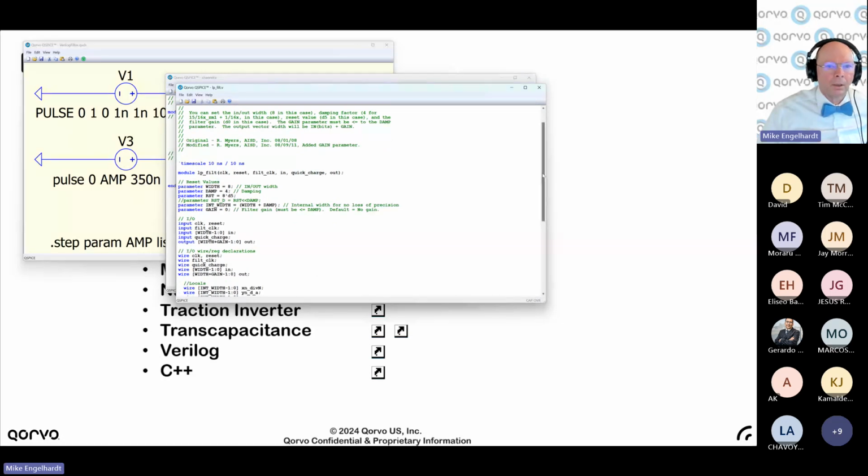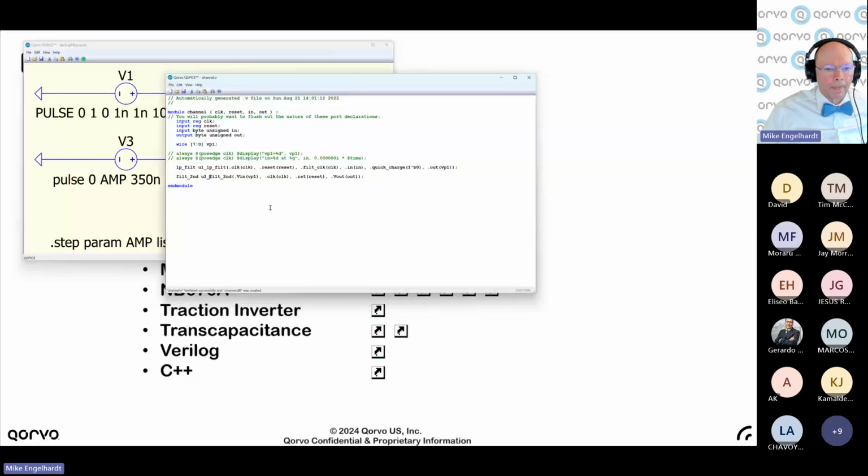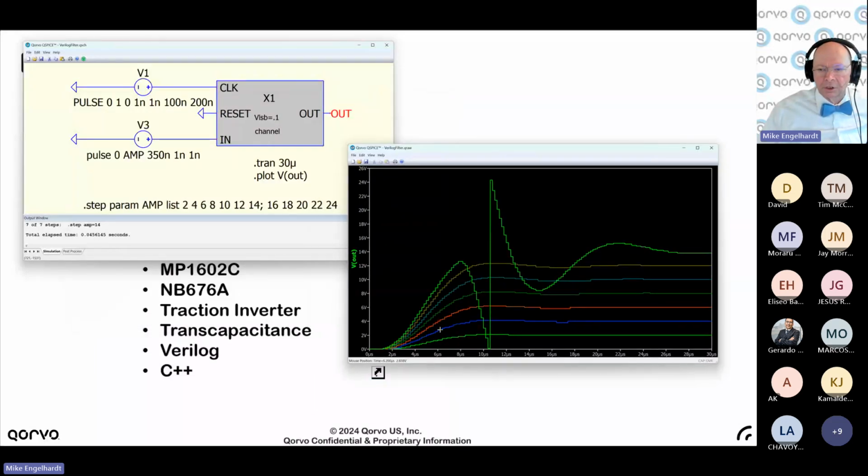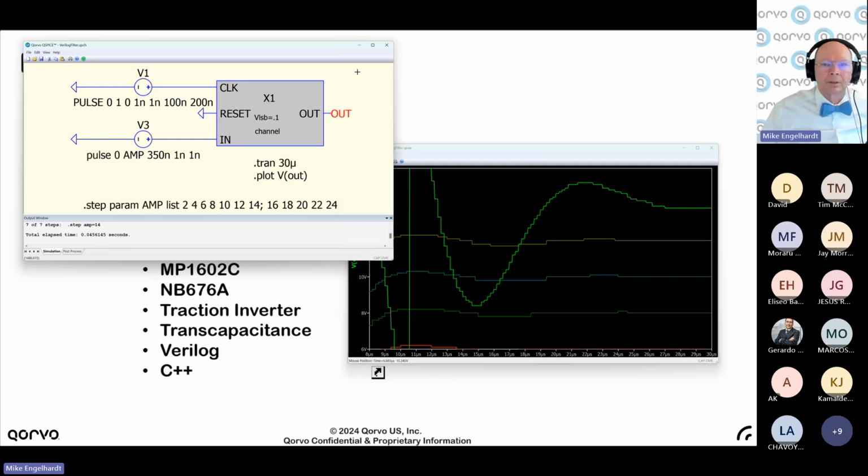written in Verilog. I actually was going to go compiling it, but that's okay. I just recompiled the thing. Open the source code. That's the source code to the other filter. And you can run this, and you can see it. It's a digital filter. It's only 8 bits, so you can see this behavior here is because you had integer rollover, and you can see the individual quantization issues because it's only an 8-bit filter.